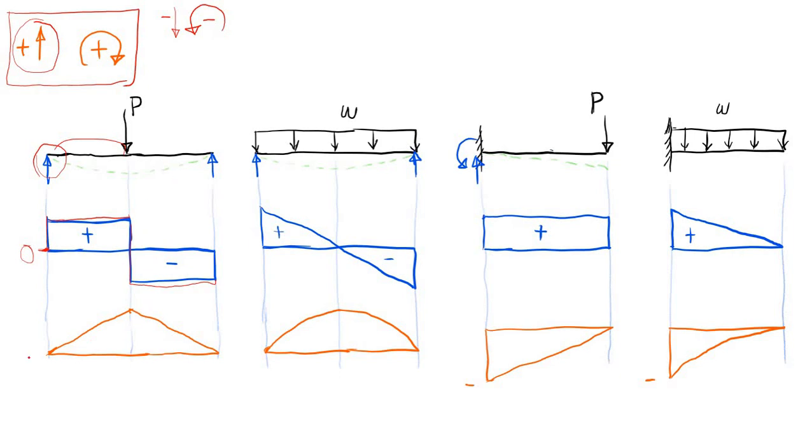Now notice, guys, that in this diagram, this is a flat line. So this is 0 degree. And when we draw the moment diagram, if we wanted to determine the change in moment between points A and B, suppose this is A and this is point B, then it is simply equal to the area of our shear diagram.